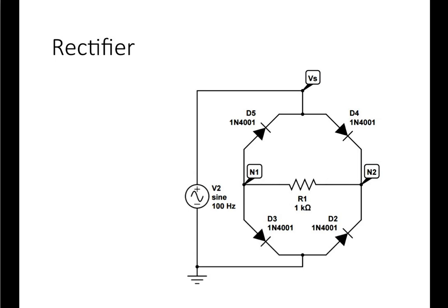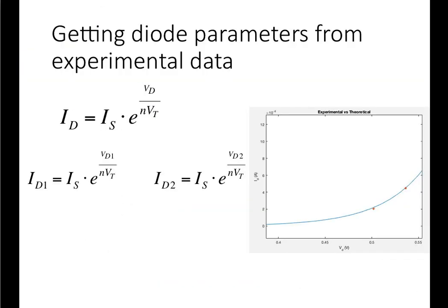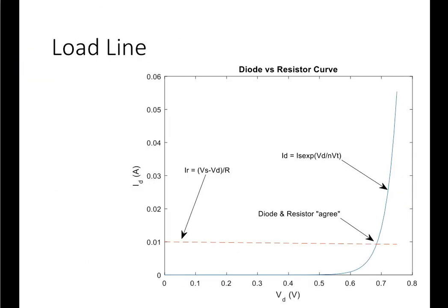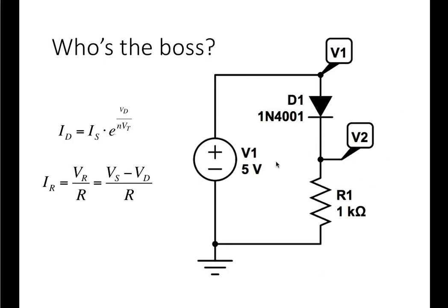One thing I did forget to say is that back in figure 1, one of the things that we do ask you there is to compute what the maximum voltage source can be so that you don't fry your components. Well, from the data sheet, you know how much power D1 can dissipate. All of our resistors up there are quarter-watt resistors, so you know R1 is a quarter-watt resistor.